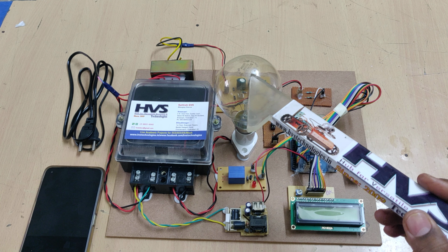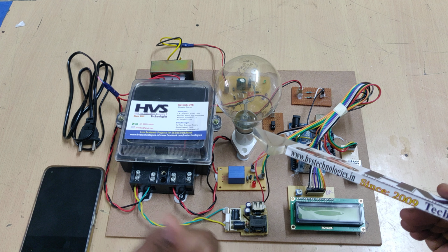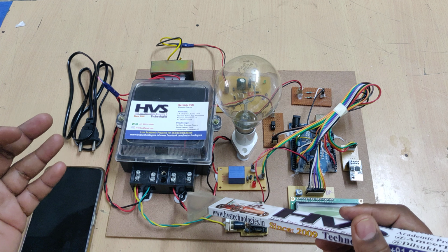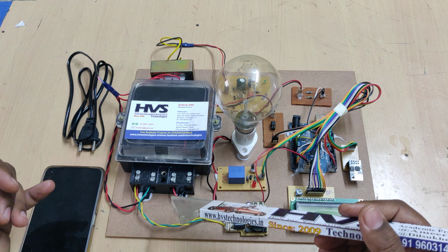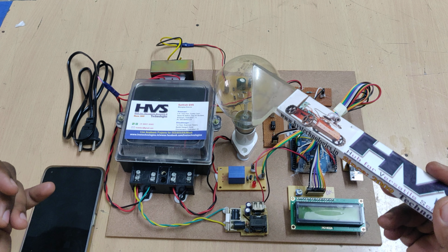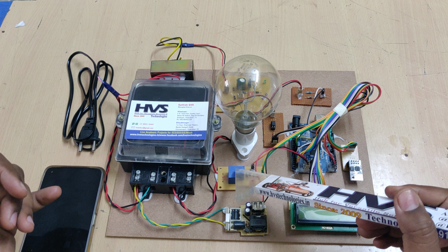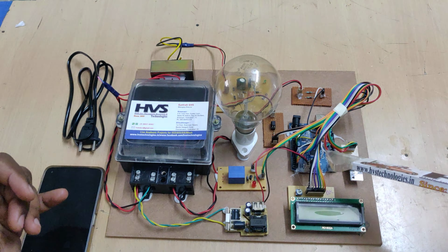So this is a 230 volts 200 watts load. Why am I using 200 watts? We can use 100 watts also, but the increase in the power consumption is slow with that rating. That's why, to make it a faster rating, we are using 230 volts 200 watts, and that will be controlled through the electromagnetic relay which is connected to the Arduino Uno board at the 10th pin.